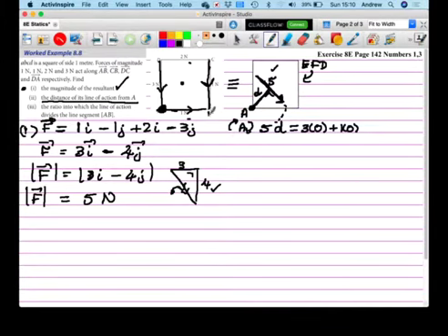Now I'm looking at this force here, and the direction of this force is downwards, which means it gives me a clockwise spinning motion, which is in the same direction as my A. So I've now got the force was equal to, can't read it, I rubbed it out, shocking. Oh, it's equal to 1. So it's going to be plus 1, and the perpendicular distance, well, we need to read the question. Each side of this square has got a length of 1 meter. So its perpendicular distance from the center of rotation is going to be 1 meter. So it's going to be 1 times 1.